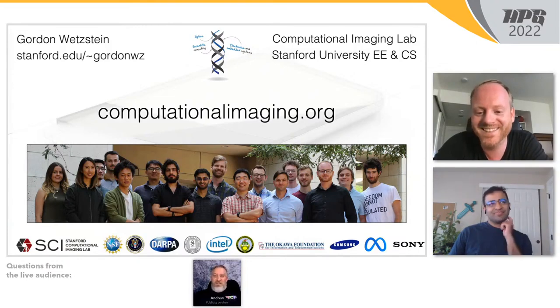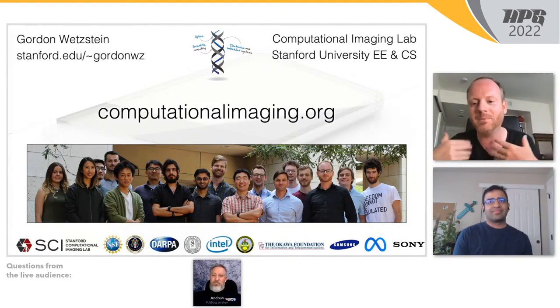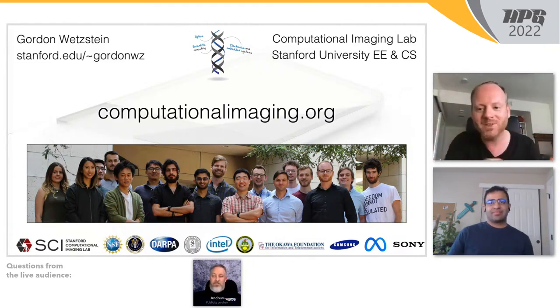So I'm just wondering how... calibration is challenging, right? Slippage. I mean, the way these eye trackers are calibrated is you have this 9-point calibration method that is happening per user, per use case, right? You show 9 points. You build some kind of a lookup table, and then you assume that the eye doesn't move with respect to the screen, and you can track the gaze, right?